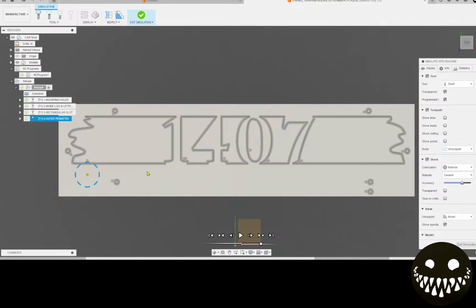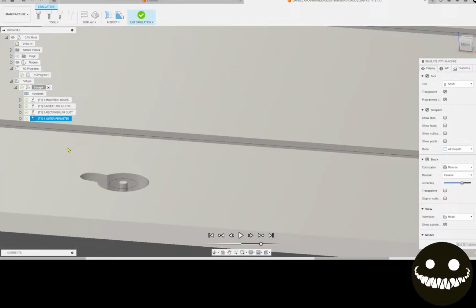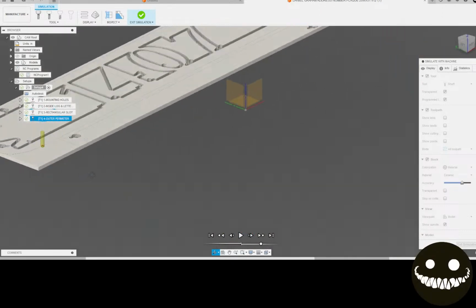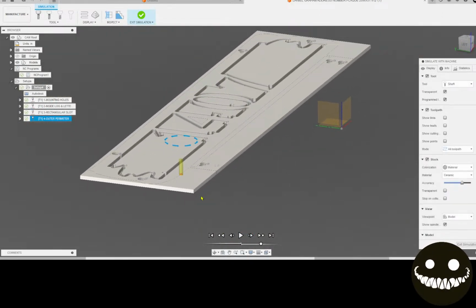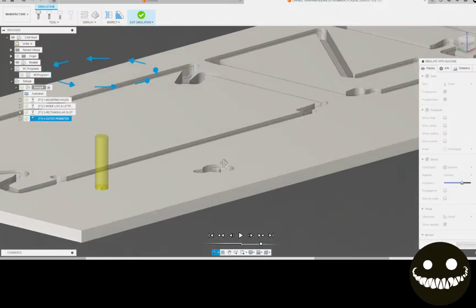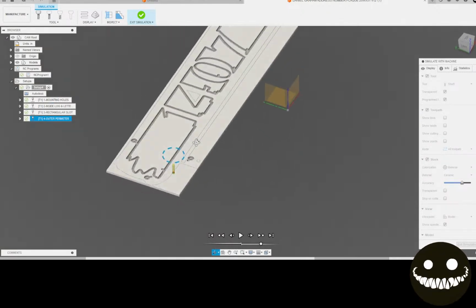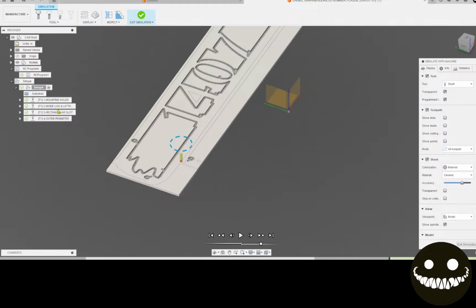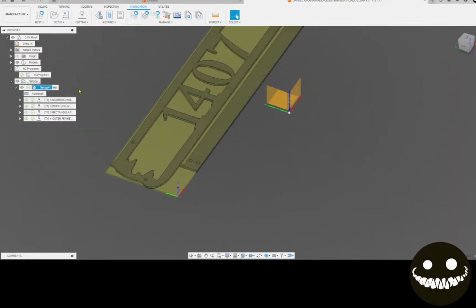Why didn't I want to show those two layers in the simulation? Well, it kind of did. It just is such a small kerf width or something. Yeah, it did cut those paths. It's just such a small kerf width you can't see it. So there are 2 different tools being used here. Let's just take a look at what we've got going on. Exit the simulation.